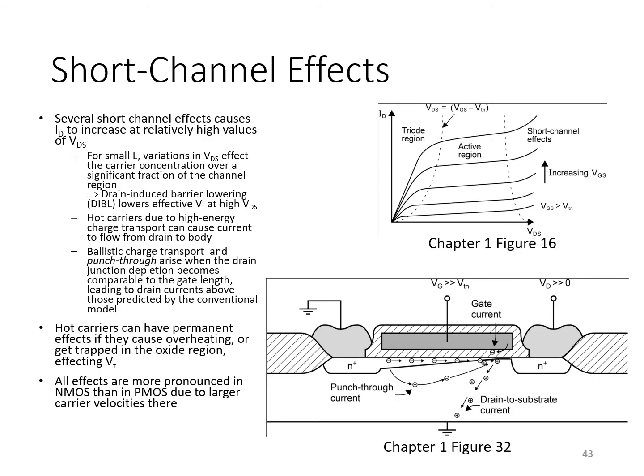There are several other short channel effects that cause the drain current to increase at relatively high values of VDS. One significant one is called drain-induced barrier lowering.